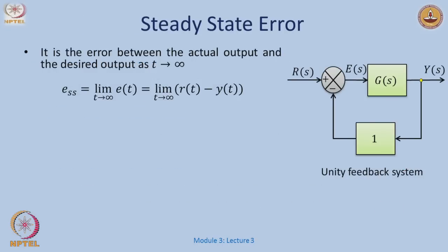Okay. So, once we do these things, we are also interested, does my output follow the reference all the time. So, we saw last time when we were doing the response for a first order system, in some cases we saw that there is a steady state error, which means the reference is not tracked directly by the output, but it is with some error which was defined by the time constant, right.